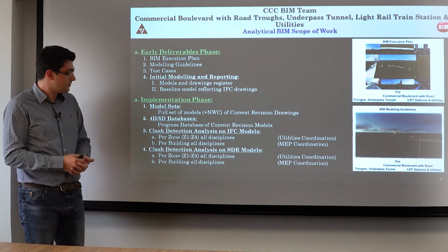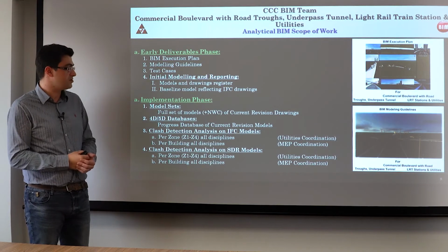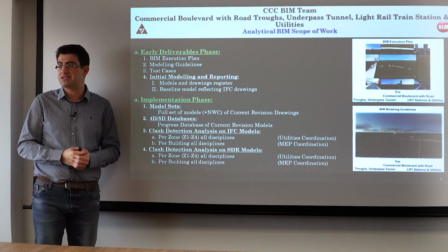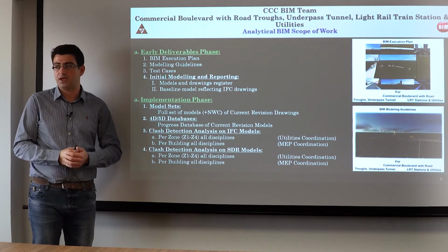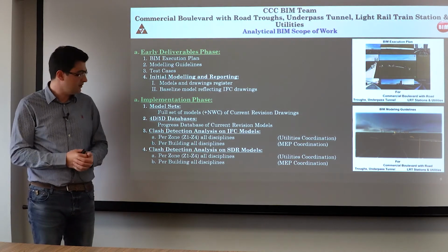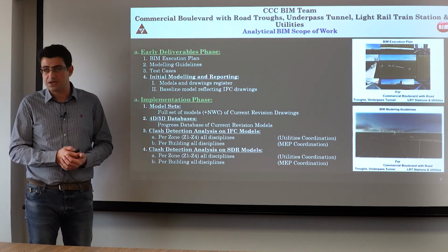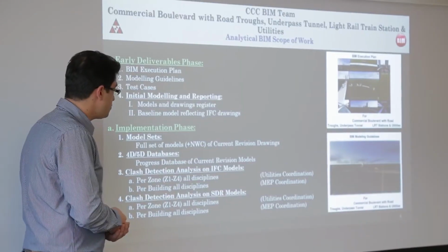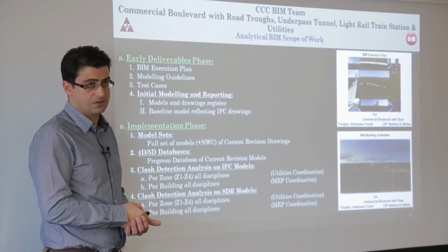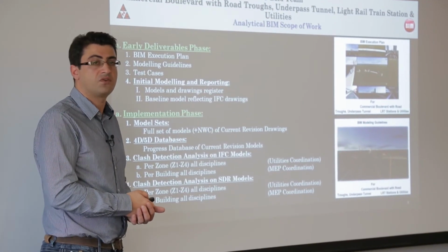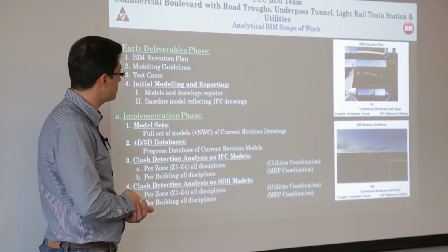Additionally, for the implementation phase, we had to do a clash detection analysis on the design models to identify all the design problems that we had from the initial design, per a breakdown that we had on our WBS. And the same thing should be repeated for the shop drawing models, because the shop drawing models may contain clashes which need to be resolved before we reach the construction phase.